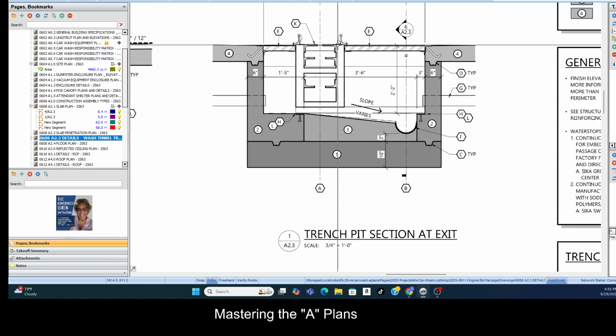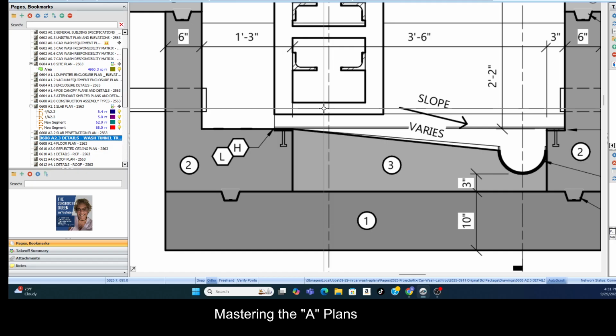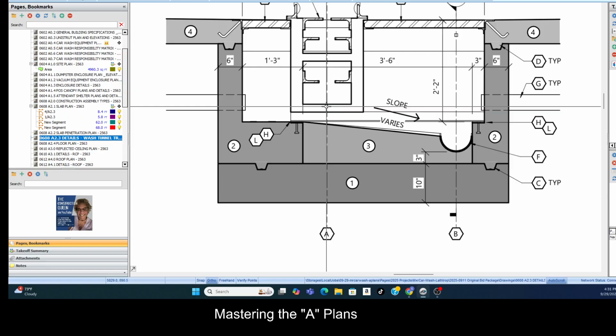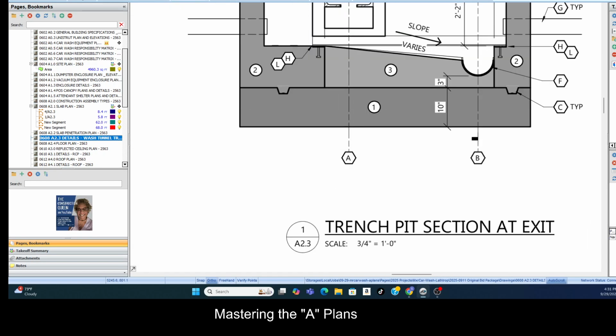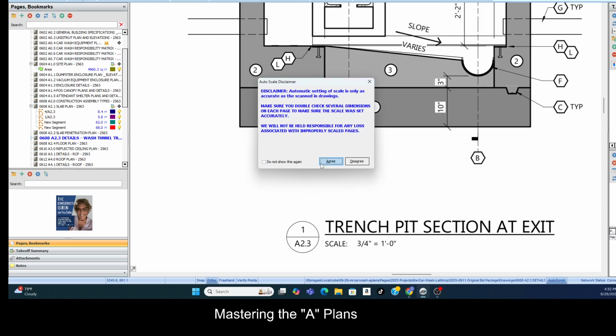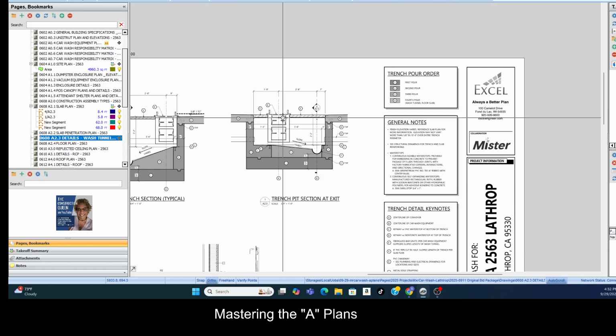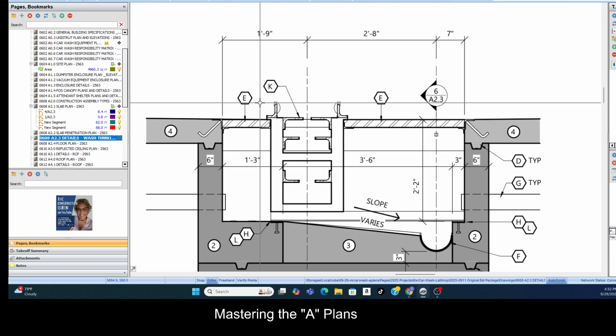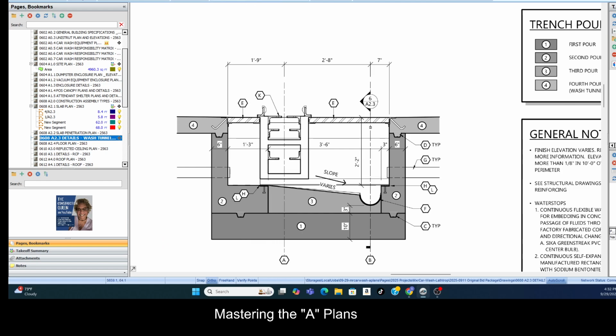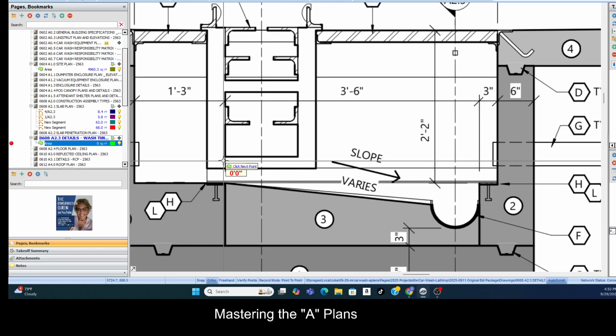So we have to determine how many cubic yards. Cubic yards are 3 lengths, right? We have 62, that's our length. So if we had to do it very specifically, we have to break this up into 2 of these. Let me do this. Let's set the scale. All right, so we know we have 62 linear feet of whatever this is. Because we're the concrete contractor, we have 62 feet of this.